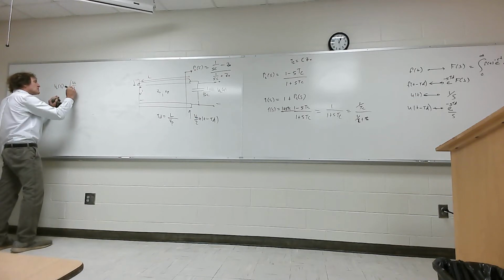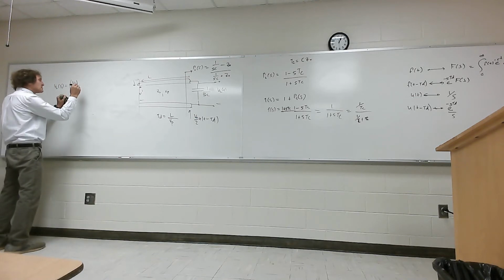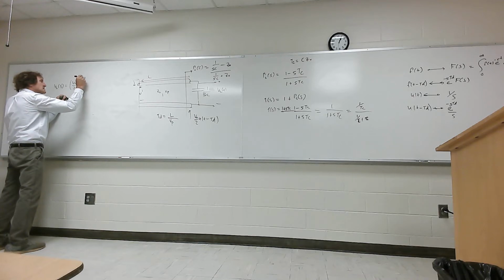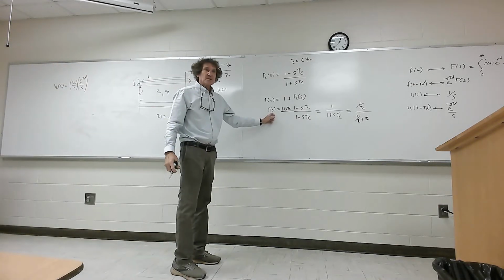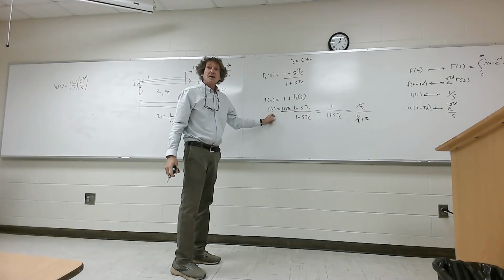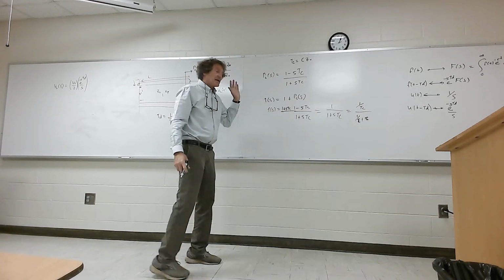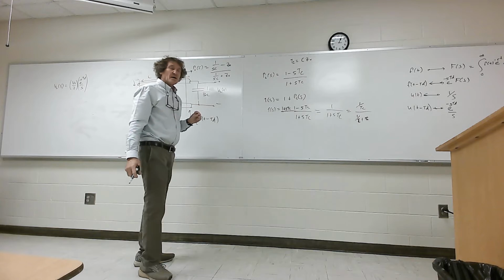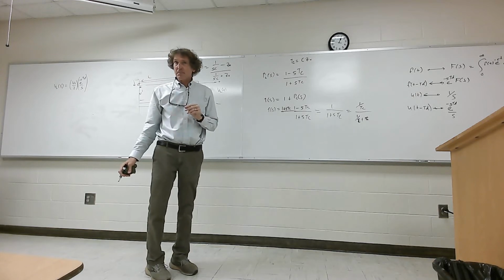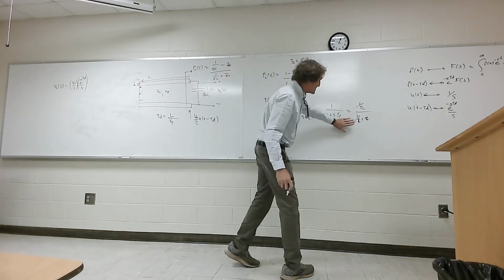So it's V naught over 2 times e to the minus s td divided by s, and then I have to multiply it by the transmission coefficient. Do y'all follow me? Once that wave hits here, I need the transmission coefficient to find the actual waveform here. Everybody okay with that? So I'm going to multiply it by this.